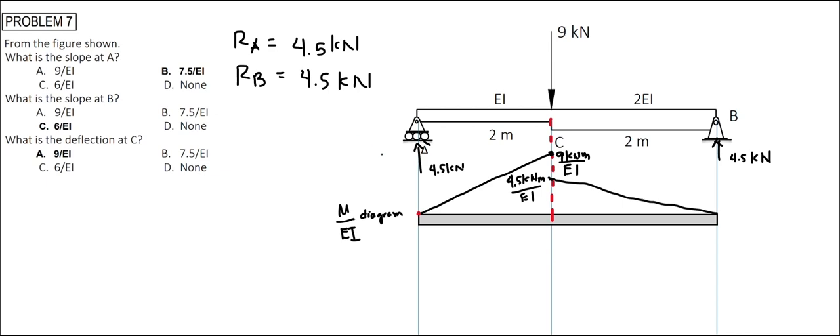So, going from a roller support, our conjugate beam has a support here that is still a simple support. So this is the same roller support as our original beam, and this one here is still a hinge support, because the conjugate beam for a pin support that is found on the outer edge is the same pin support in the conjugate beam. And then next, we solve for the reaction at the support of our conjugate beam. So we let this be R sub A, and this one is R sub B.